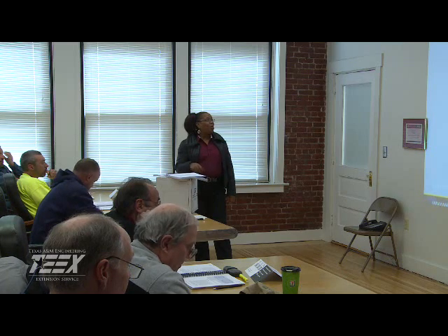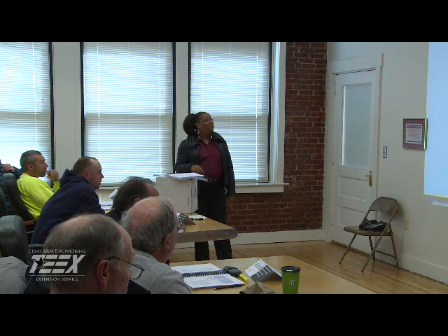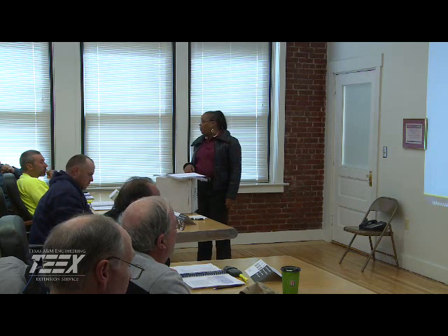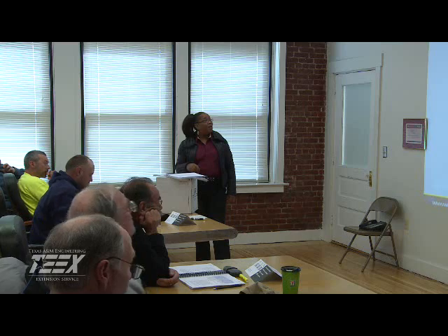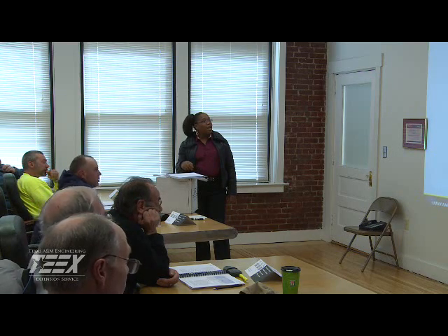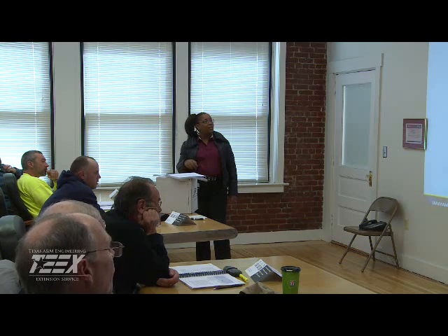So make sure you have a good map of the distribution system and the location of where everything is. And then again, we're picking sites that are representative of the various size mains, as well as farthest from the location of the production site. Okay?